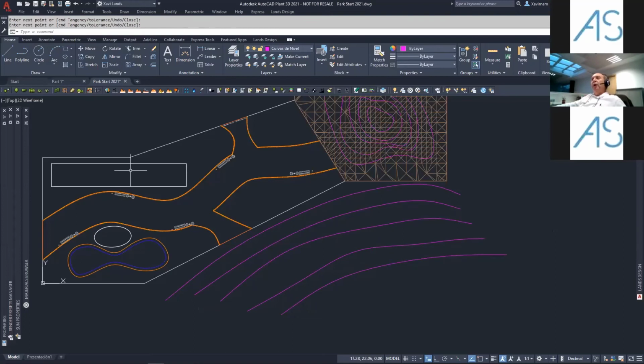If I want to constrain my area, I can create a polyline that is going to follow, using the reference points, this point here. Then I can use any of the AutoCAD commands to close this area that I want. If I want to make just the terrain, this area constrained. Then as you can see, we can create open or closed splines.